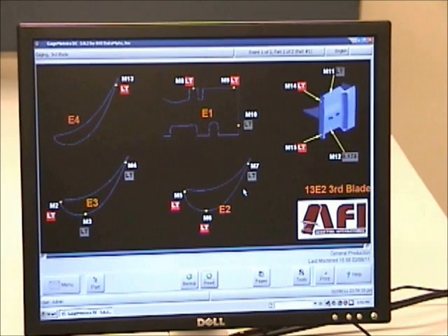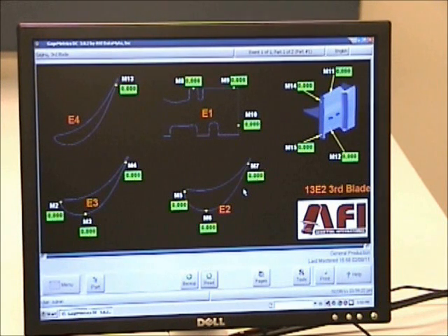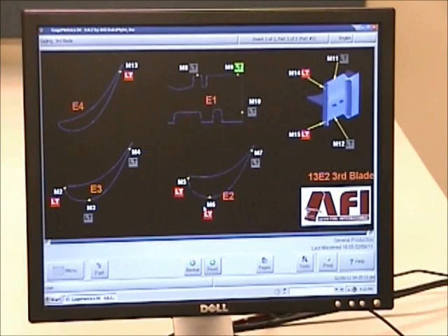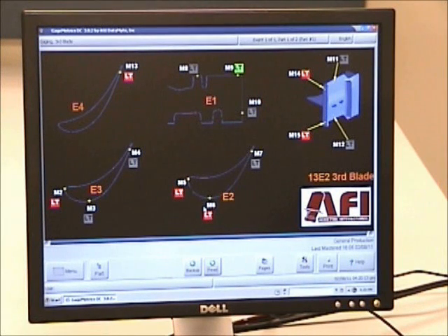I'm going to deactivate and reactivate, and this should measure exactly 0 because we have the set master in place. So at this time we're ready to gauge a part. It's important to get the transducers set the right length away from the part.